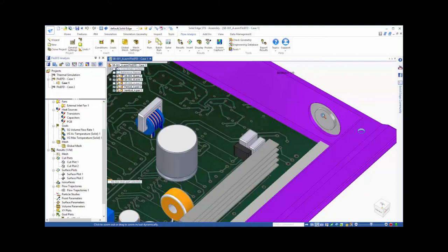One of the ideas that we would like to test based on our first solution is to shift the fan slightly towards the center of the amp. We are hoping to divert a portion of the incoming airflow more towards the central region of the board to cool those components better, while still maintaining strong flow through the heatsink. Additionally, we will go ahead and increase the length of the heatsink fins to further help cool the transistors.